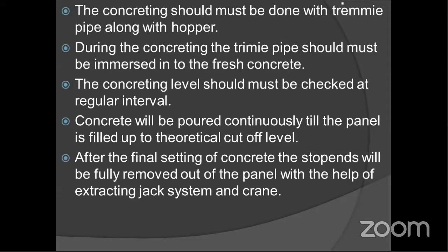The concreting should be done till the theoretical cutoff level. Before starting the concrete, we did the CBH, and we have also decided the depth. So based on that depth only, we should put the concrete up to that depth, because after the D-wall we have to do certain constructions like the capping beam, retaining wall and all. For this and all these things, we have to know the cutoff level of the concreting.